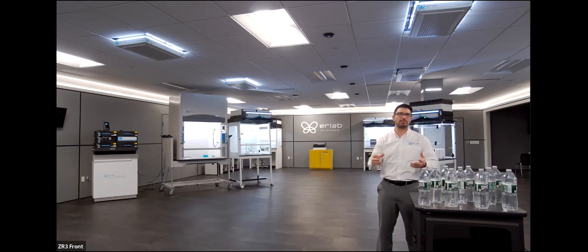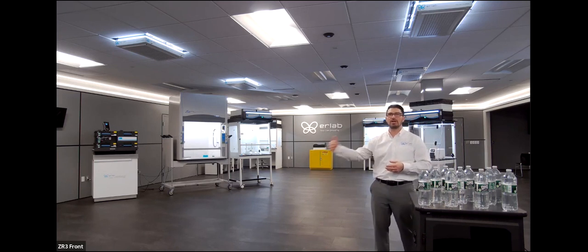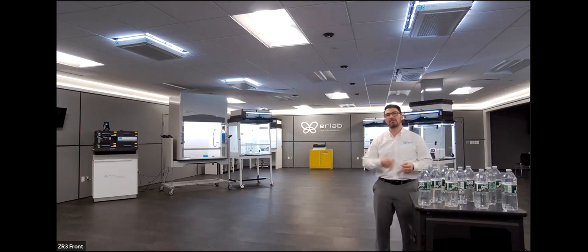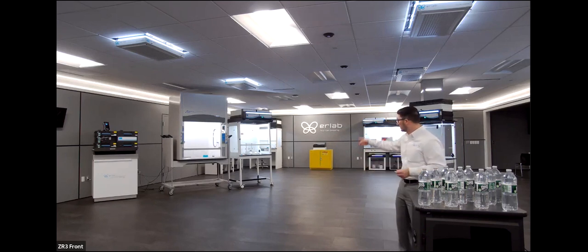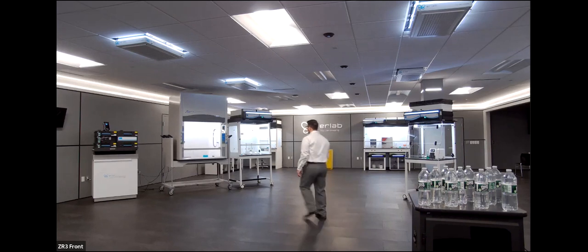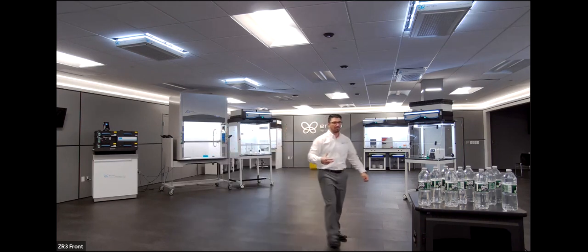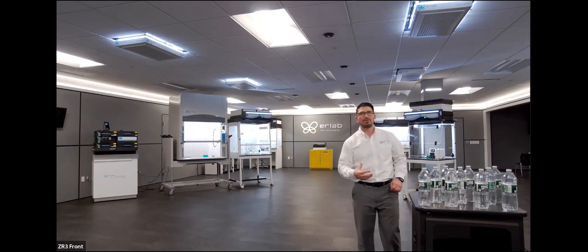If any one of our products are failing for whatever reason, that light will pulse, followed by an audible indicating system that will alert you of what it's failing. So for the hoods behind me, containment's critical, right? We have to meet ASHRAE 110 standards, so that's air face velocity entering the hood. If that's compromised in any way, let's say the sash is left open, and I'll actually open it up, this is a sash, then that light will pulse on either system to give you an indicator that it's not operating at peak performance, and it helps improve overall laboratory safety.